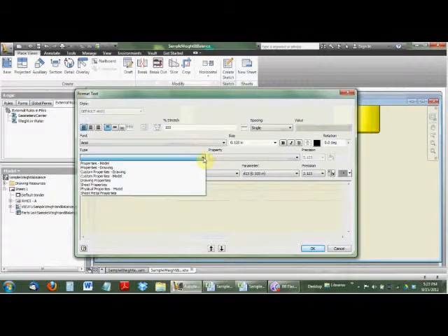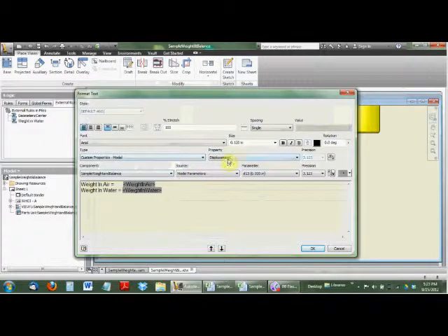You get these iProperties by going to Custom iProperties Model, and you go over here and displacement has come up. I don't have displacement here, so let's just put displacement right in there. So by clicking on this little add a text parameter, these really aren't parameters, they're really custom iProperties, but it does the trick.